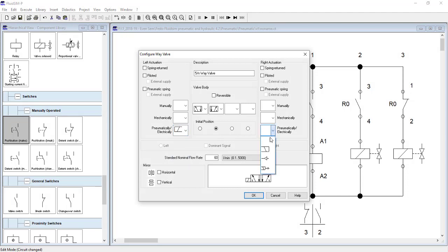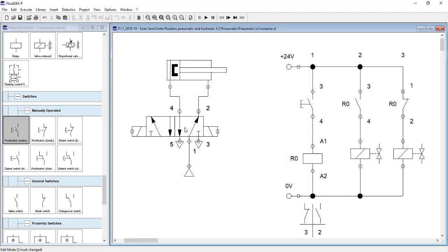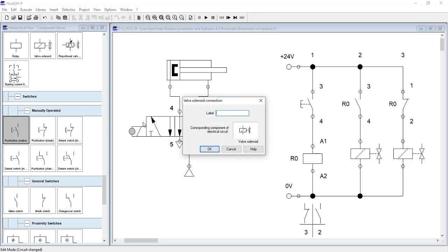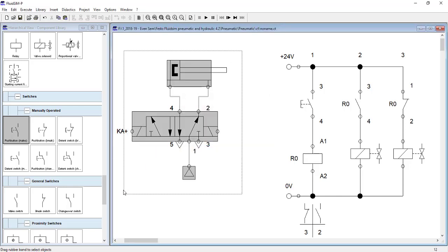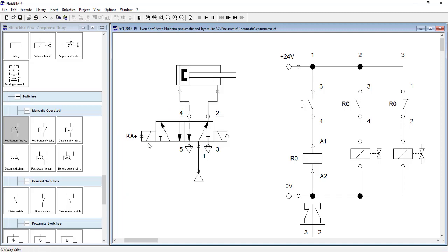So as this is an electropneumatic circuit, I will have to use solenoid valves over here. Right? These are my solenoids. This is a solenoid operated spring return valve. So let us name this solenoid with our normal pattern. This is Ka plus, because for solenoids we use the symbol K, and it is causing A plus motion, forward motion.